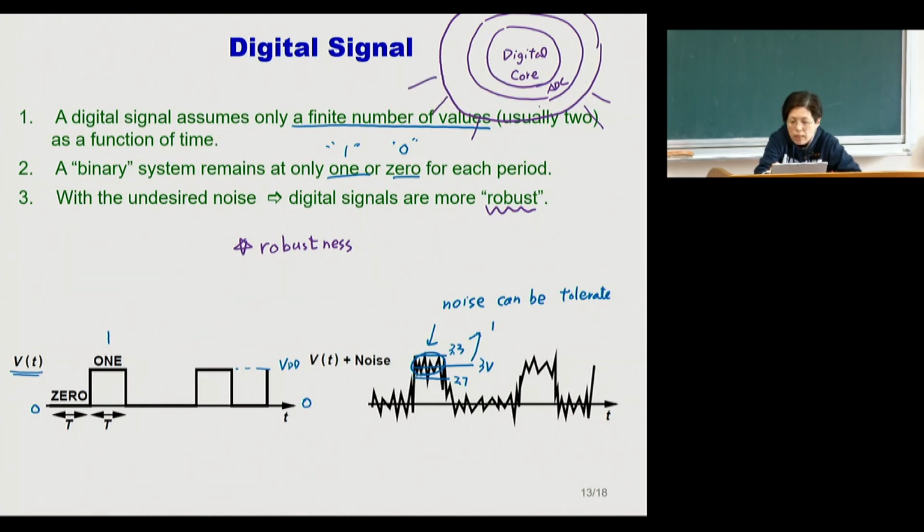Whatever signal is coming in, you will have some analog components to pre-process the signal. The analog part is the interface with the natural world, because natural signals are analog, and you have to deal with them. Once you pre-treat it and sample it, you dump it into the digital system for further processing, calculation, manipulation, everything other than pure computation, and it will be done in a digital core.